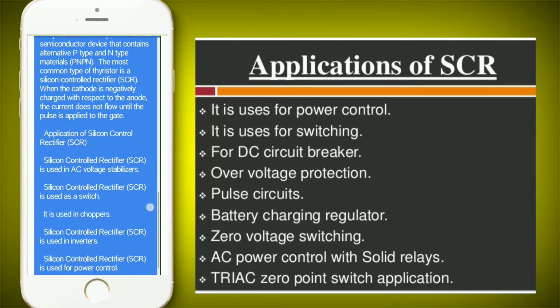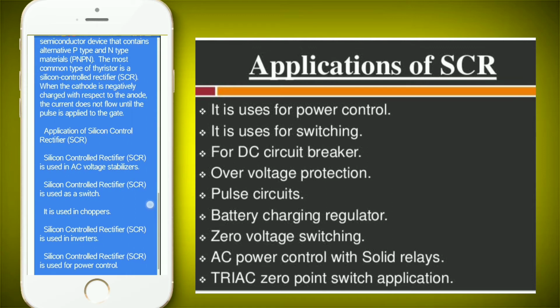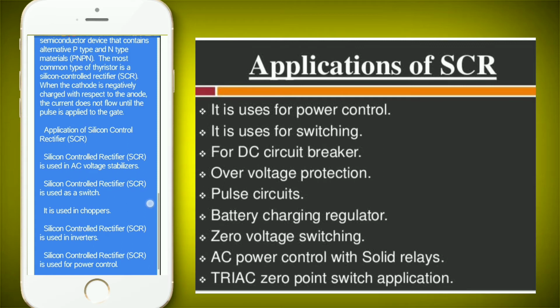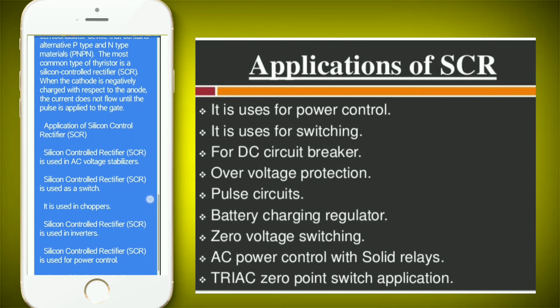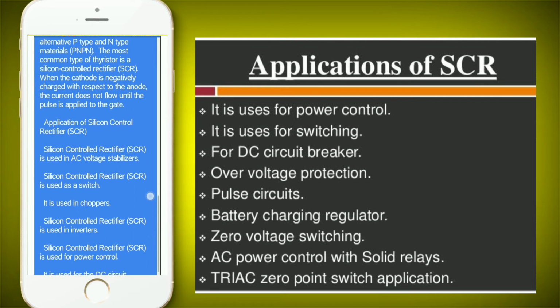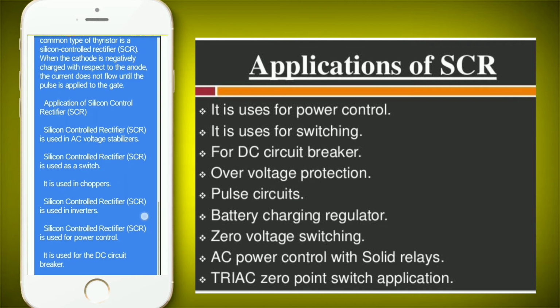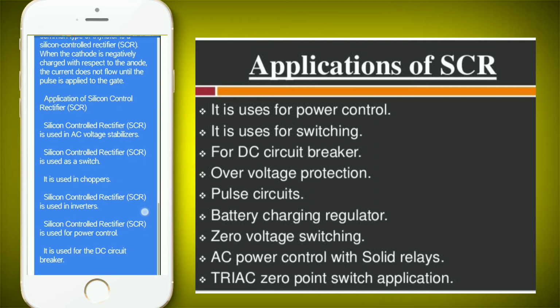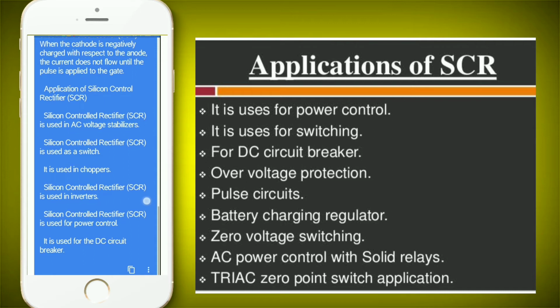Application of silicon controlled rectifier (SCR): it is used in AC voltage stabilizers. It is used as a switch. It is used in choppers. It is used for power control. It is used for the DC circuit breaker.